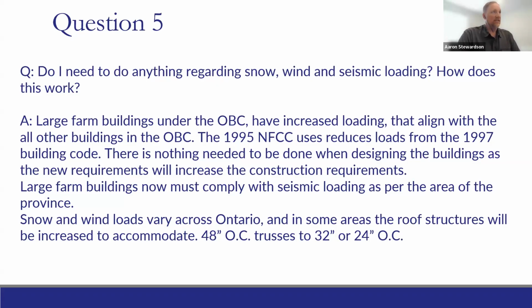So yes, there is, depending on where you are in the province, right? Like here in Huron County and Lambton County along the lake, the seismic is very low, right? As you move towards Niagara and you get down to Norfolk and Haldimand counties and over up into Ottawa, the seismic loading is larger, right? So this is where, go back to the other question, can I design my own farm building? That's the situation when we get into the seismic loading and the snow loading. That's where you need to hire that qualified person, that professional to provide you with the math to ensure that these buildings are constructed to those new loads.